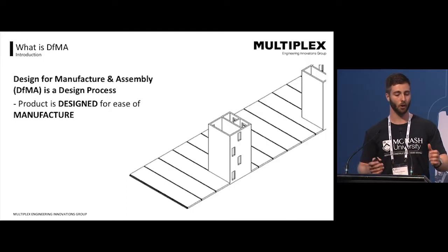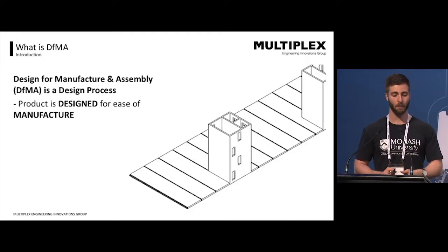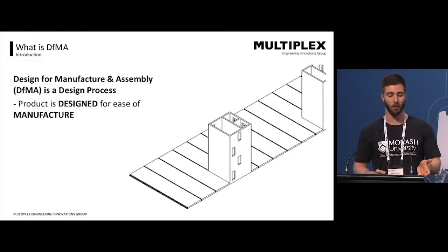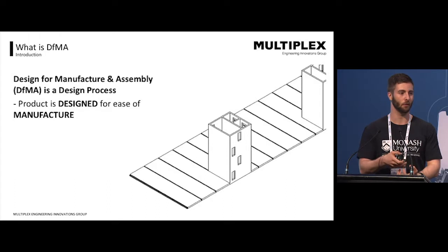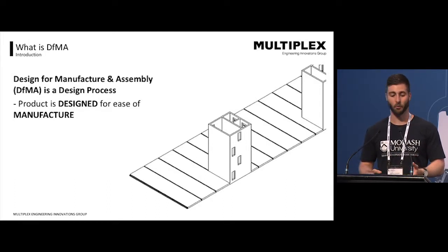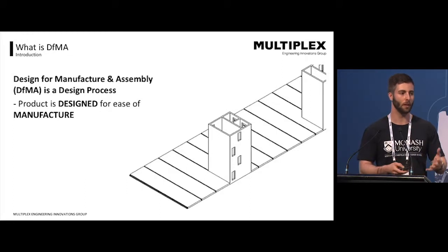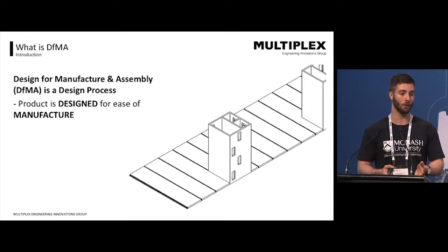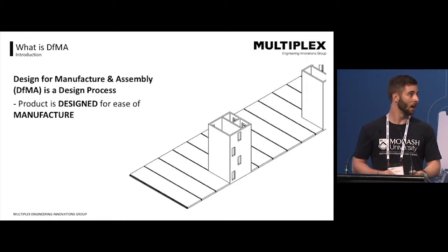Basically, a frame gets dropped into place by a tower crane. The guy goes along on the scissor lift, and from above, he's able to access the bolted connection. Threaded rod feeds down to a box bolt at the bottom. Basically, that clamps the two columns together. So there's no temporary propping required. It's a very simple, very quick installation process. So we're saving on time, we're saving on materials, and also on the labour on site.